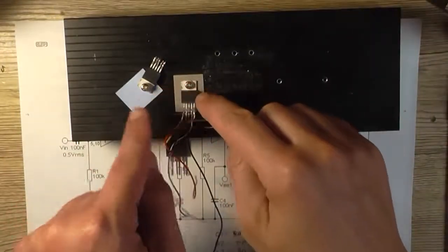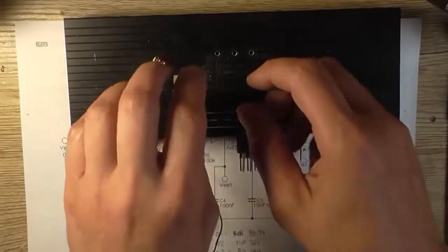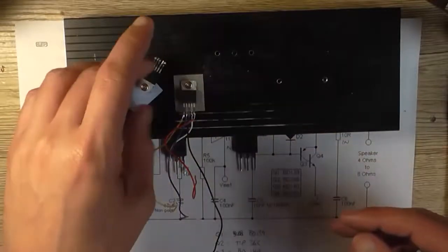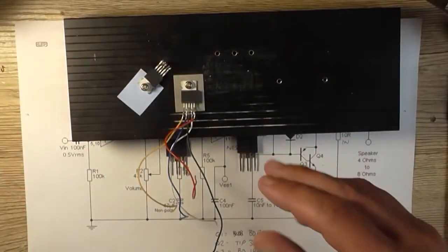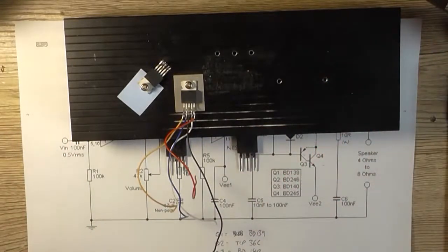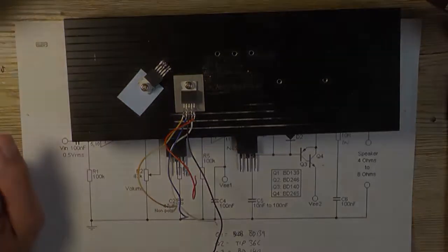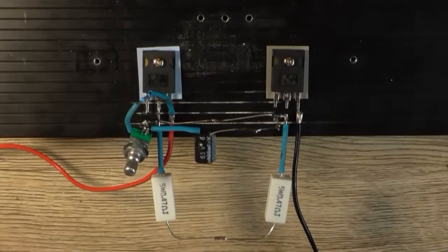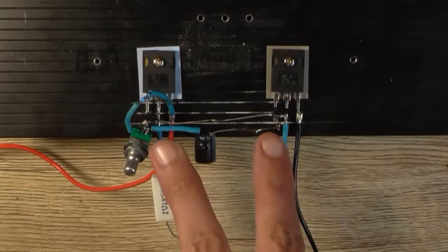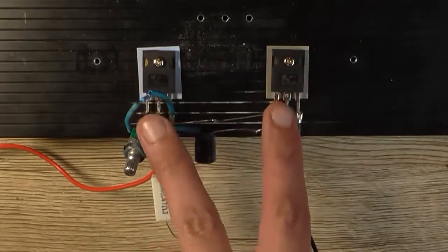and just like this, all the components will be wired between the pins, and it's called dead bug because things are standing up and facing different directions and it's not neat and it looks like crap, whatever. And that's what it's called, dead bug style. So that's what I'll be doing. So first I'll get the output stage all buttoned up here, and then we'll look at testing it on its own. And a short time later, here it is wired up. This is what I meant about dead bug wiring. Here's our two biasing diodes, which are roughly in contact with the two driver transistors, which are sitting here.